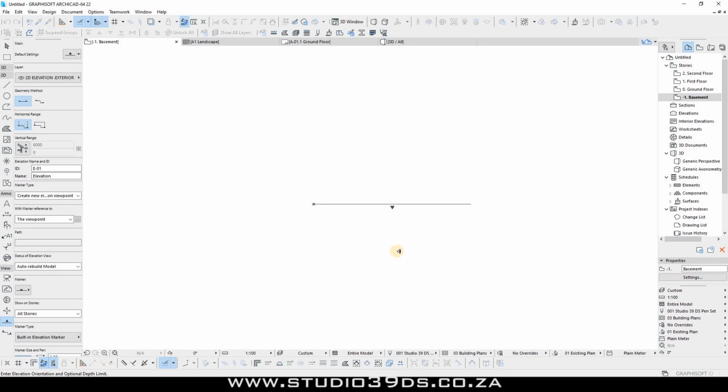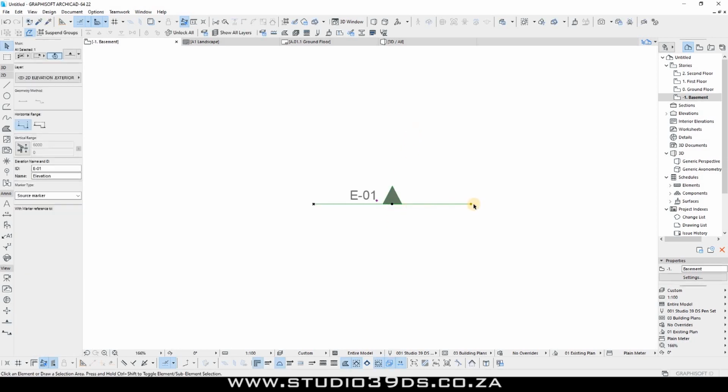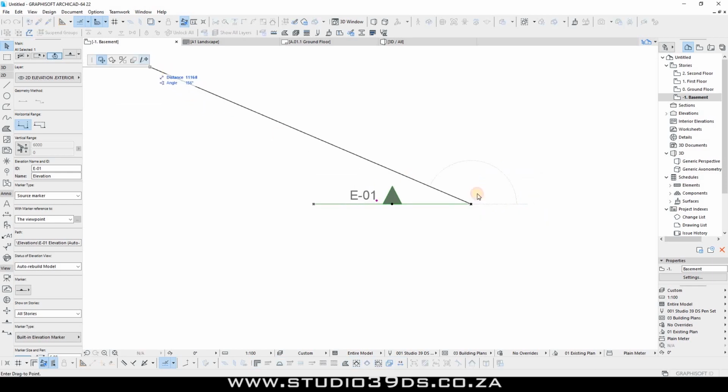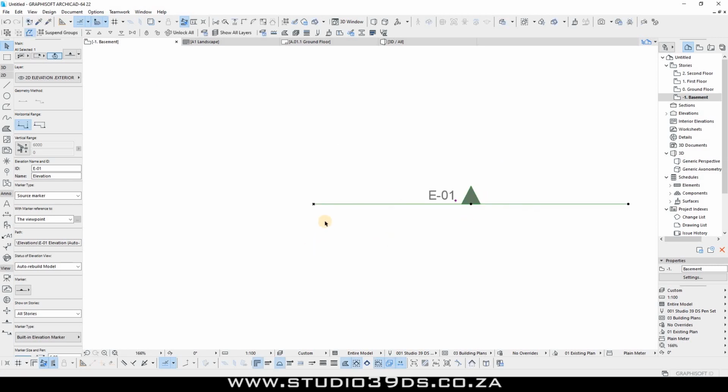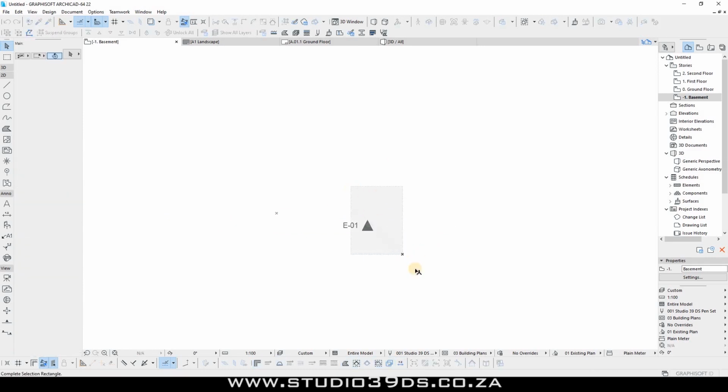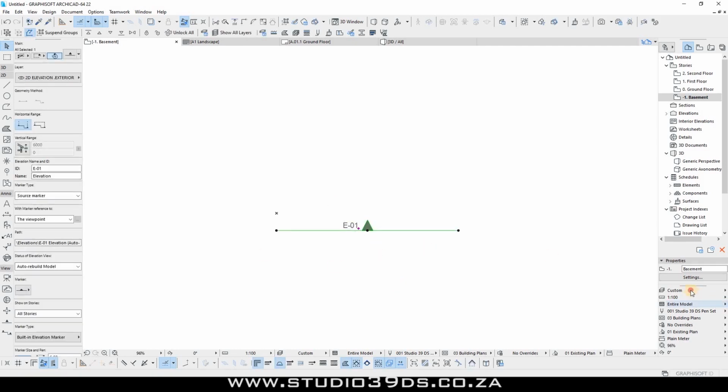And then it's going to ask me, using this eye that's indicated on the workspace, whether I want to point down or point up. I'm gonna point out for now, and as you can see, maybe I can even extend this by extending it to like 10 meters. There you go. Bring it down maybe by a meter, and you can see that because I changed my pen set, this information is not showing the way it's supposed to be showing.